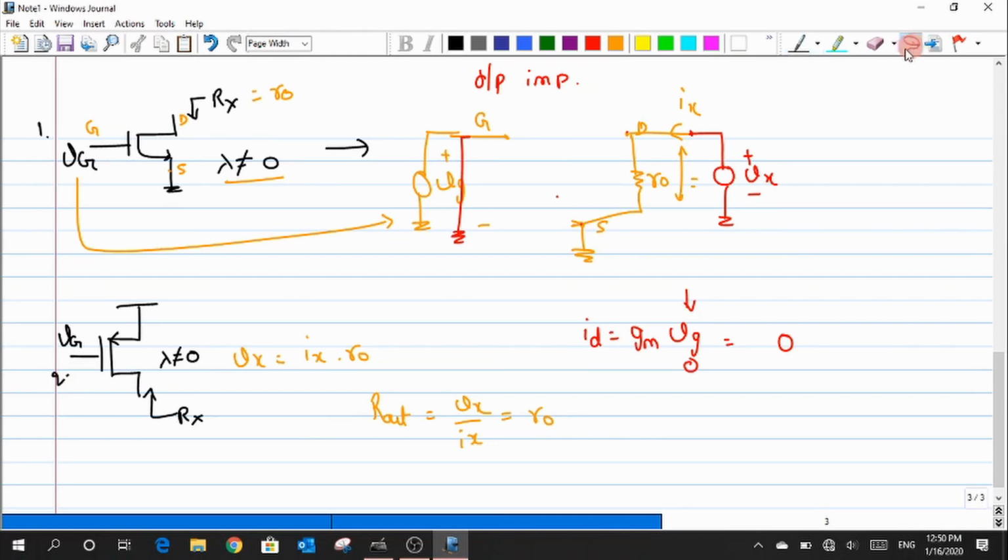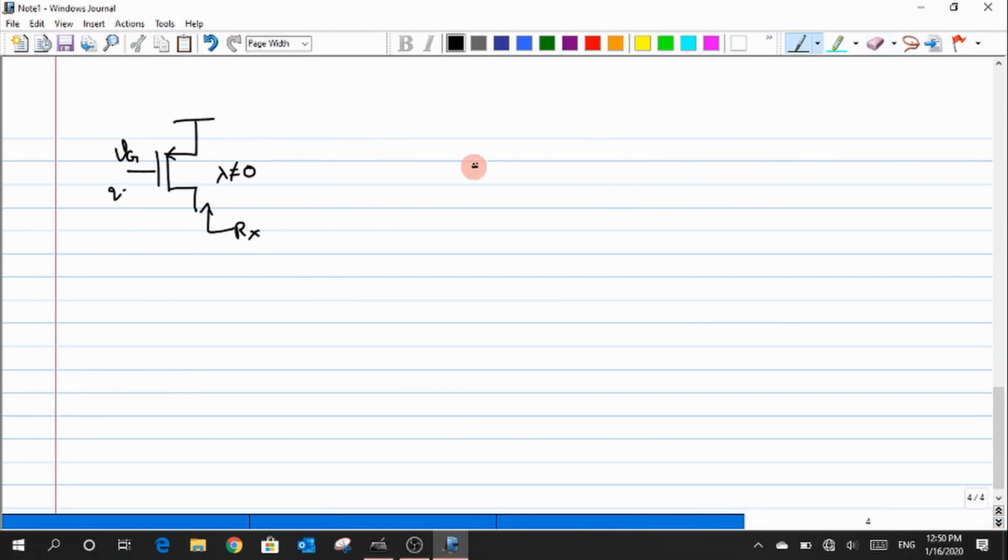So I'll carry the circuit to the next page. Now I just try to draw the small signal model. When I look here, I plot all of these three nodes. That is my general way of doing the small signal model. So this is my gate, I fix my source here, and the drain is here, and I have this VG. And what happens to this VDD when I translate to my small signal model, which is connected to the source? That is grounded, so I have this.